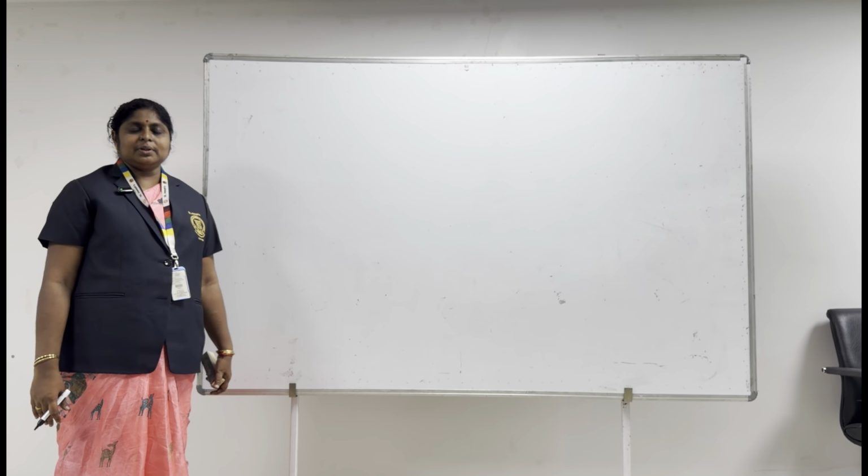So, in all inputs I0, I1, I2, I3, content will be there in all sequences. Depending upon our select lines, that particular content will be taken as the output. So it will concentrate only upon the particular input based upon our select line. This is said to be a mux. That's why it is said to be a data selector. It selects the input data and takes that as the output. That is why this circuit is said to be a data selector.